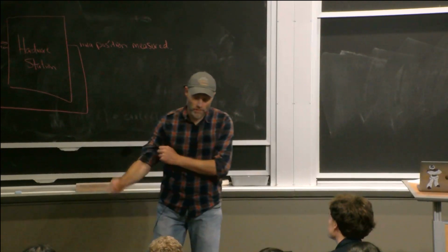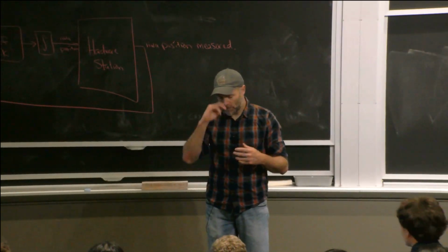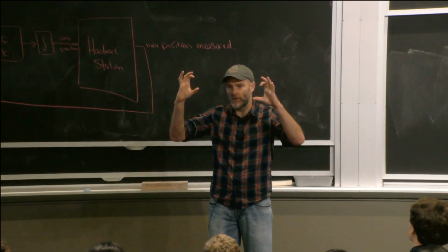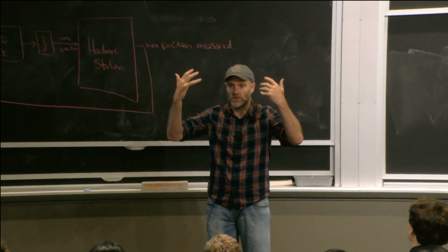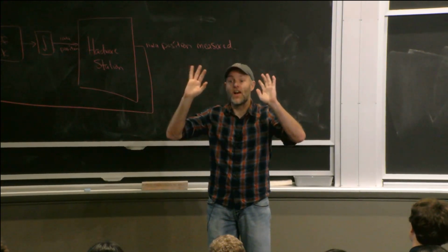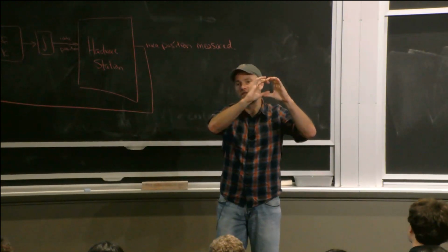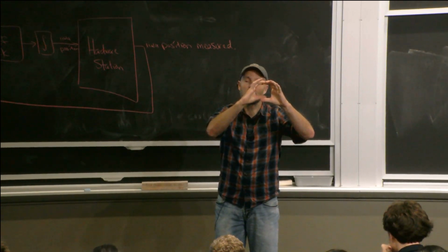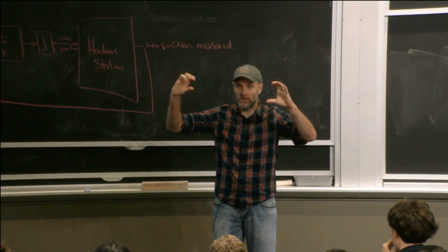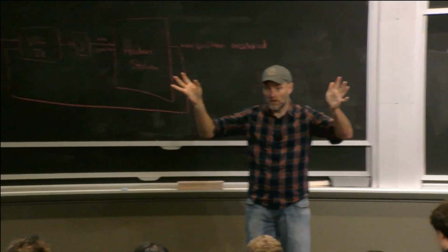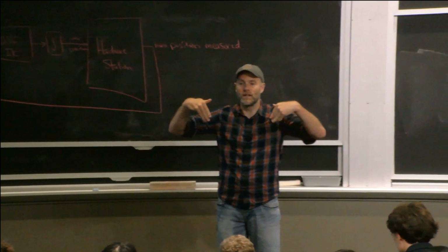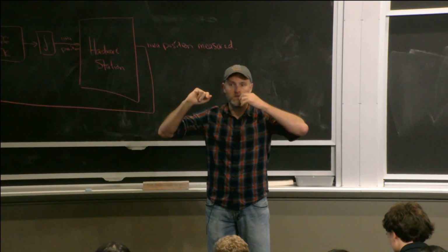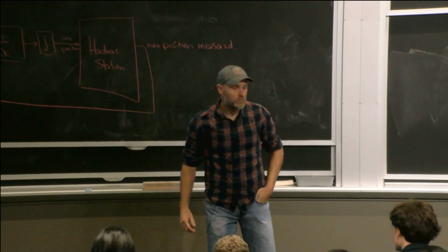The question is, I mentioned FPGA and the Carnegie head. I think that if you're doing block matching stereo, that's the simplest algorithm, and they're doing more than that in those heads. But that's the essence of the hardness in the computation: you're doing a relatively simple computation, taking an 8x8 block of pixels and comparing it to another 8x8 block of pixels. But you have to do that for all possible pairs in a row, for instance. So it's a very trivially parallelized operation. And in order to get operating at full frame rates, computers have gotten faster and faster, but it's just a beautiful solution for specialized hardware.